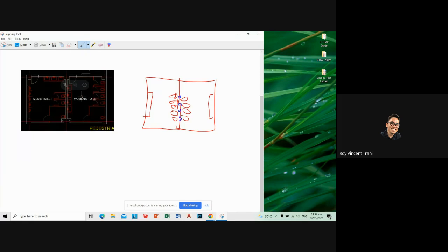This will make it easier for the sanitary engineers to lay out their piping. Usually for toilets, I think it's about a 10-inch diameter here, and then the lavatories are I think 5-inch or less. So this way there's less separation and the piping is simpler, and this will make the engineer's job easier.